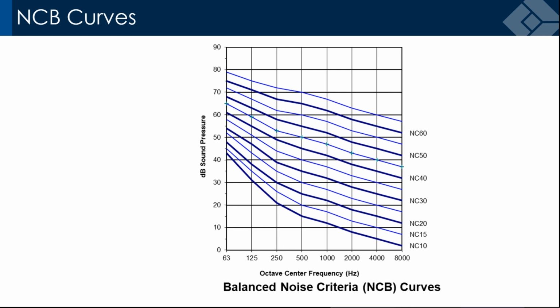Exactly. And I think there's some points where the easiest thing that everyone goes to is, do we need a silencer? But it really depends on where in the system it is, because acoustics is an entire system. And there's sometimes where your air handler, where everyone puts their silencers, is not the controlling noise. If you get to the end of a system, your terminal box might be louder than your air handler unit at that point. So adding a silencer upstream doesn't do anything. So it's these little things where there's no prescriptive method. You can't just say put a silencer in, you'll be okay. There's a lot of different components that make noise. So that's something that we'd like to get everybody a little more comfortable with, knowing where in their system they might have to look.